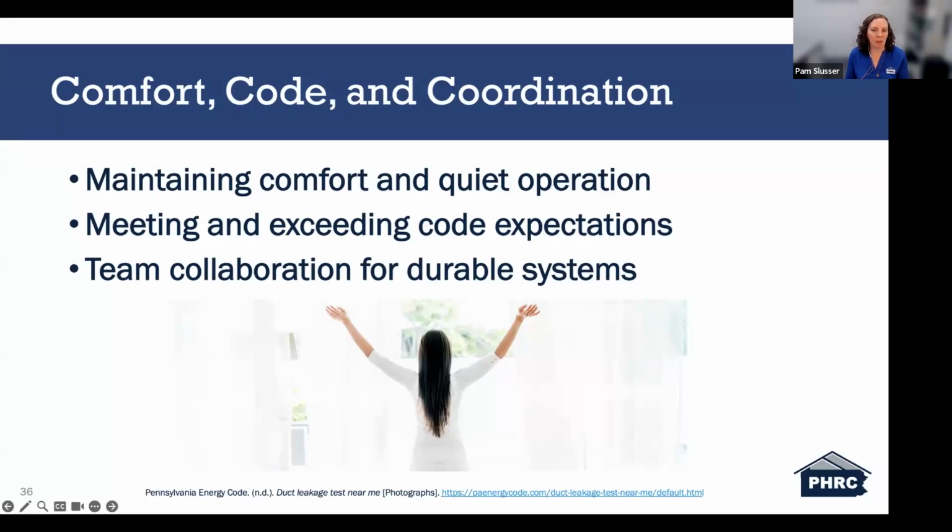First, maintaining comfort and quiet operation is the end goal of a properly designed and installed system. When the ducts are sealed, properly sized, and located within the conditioned space, we reduce those drafts, temperature swings, and any noise issues. It also makes for a happy client when you have all of those met.